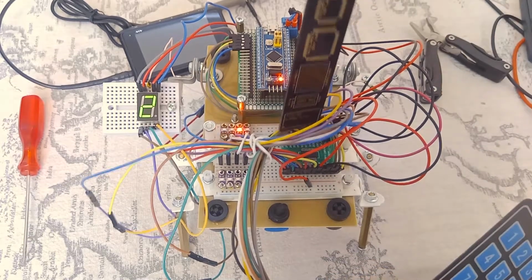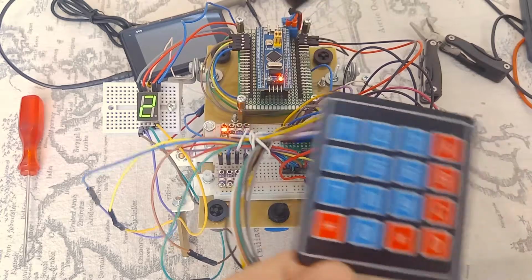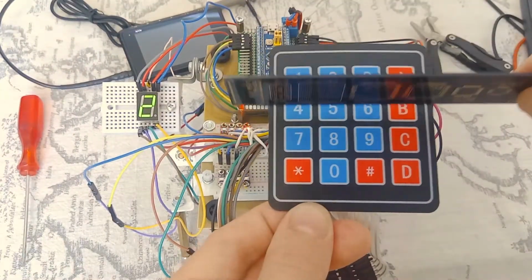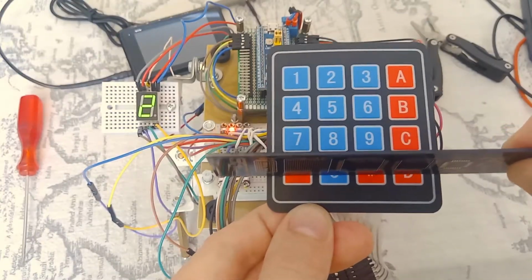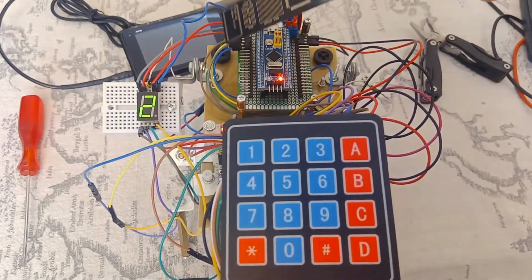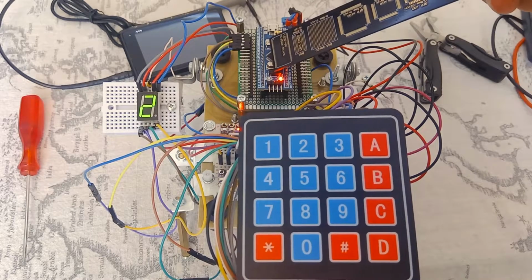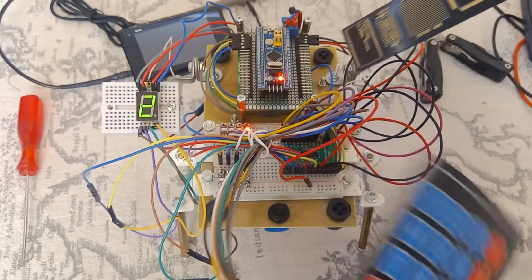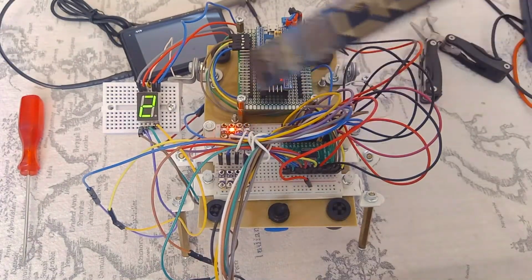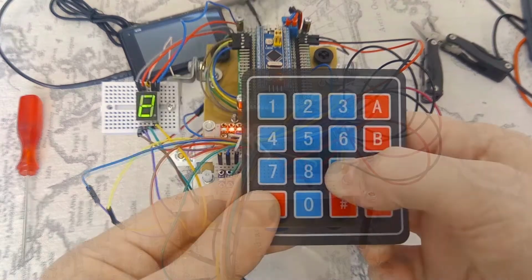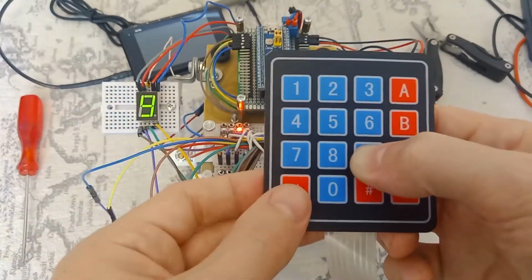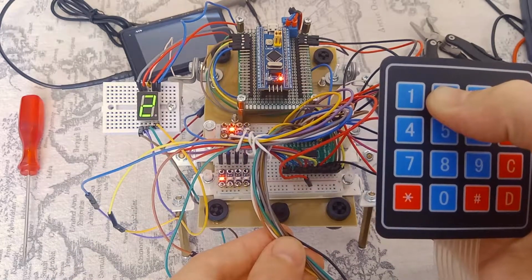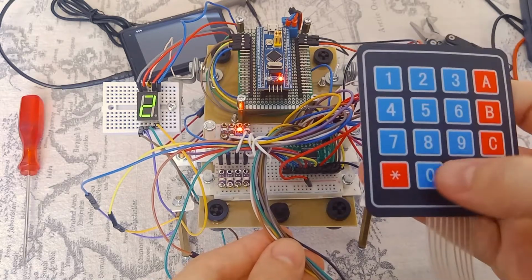All this is done by the input-output expander. Keypad power and read lines are connected to this expander. After we read a certain key, this data gets through SPI into the microcontroller. It analyzes this information and issues a control signal back to the expander in order to show the figure on the 7-segment display. That is, when we press the keys, the values of these keys are processed by the microcontroller and it issues a signal to display numbers in 7-segment form.